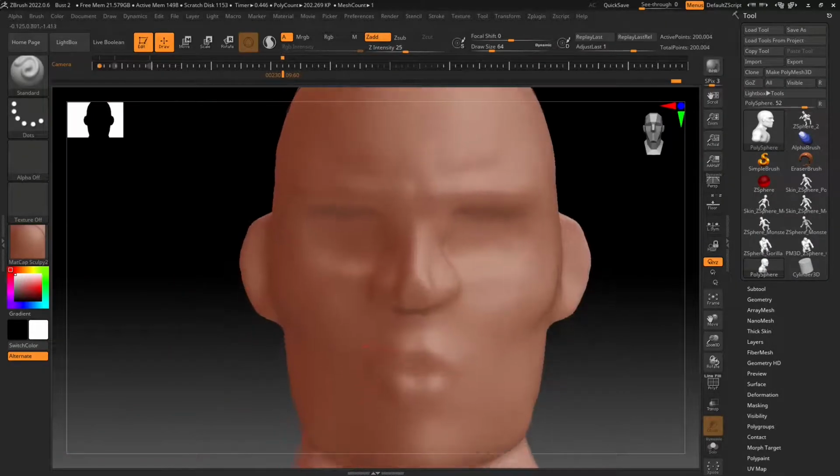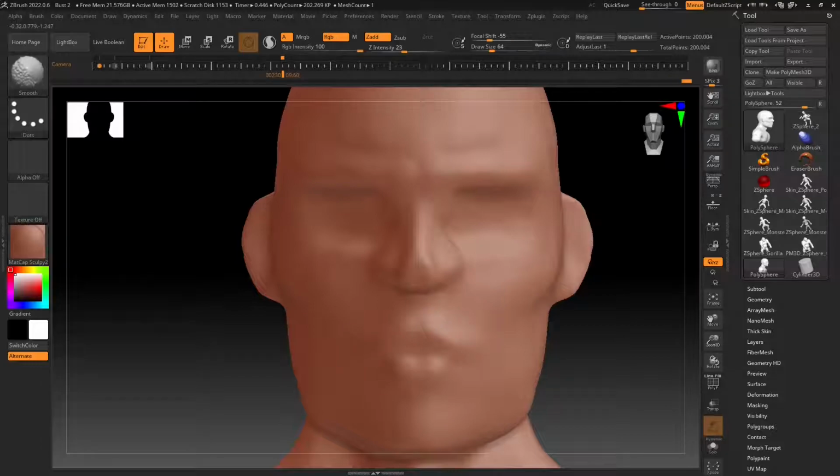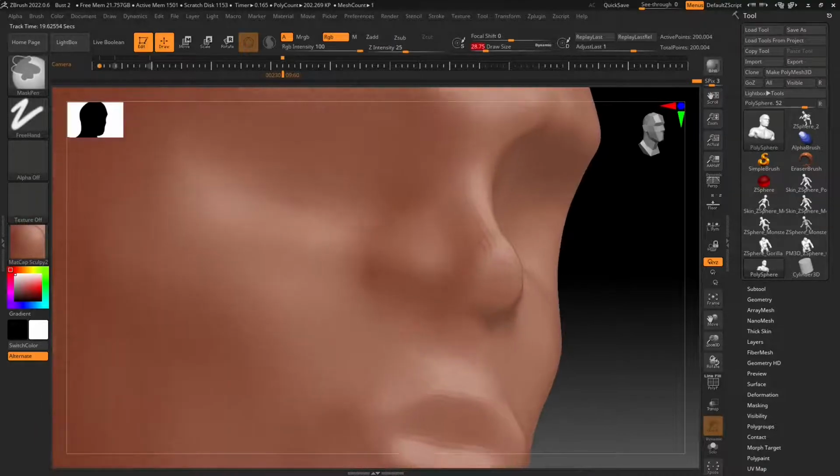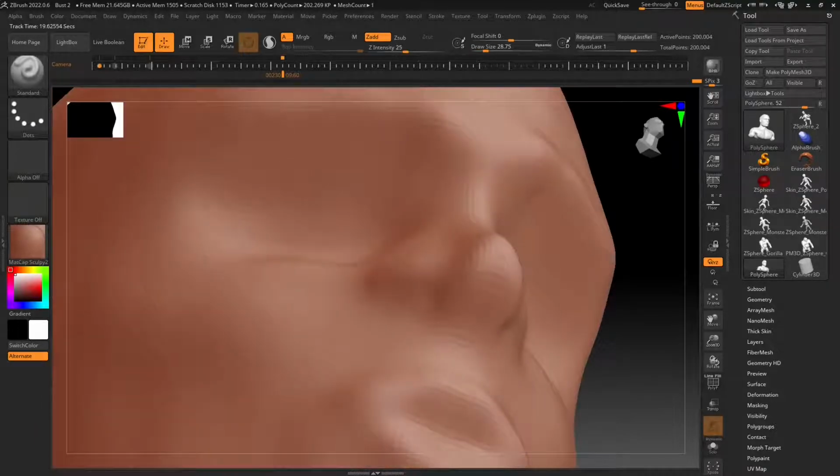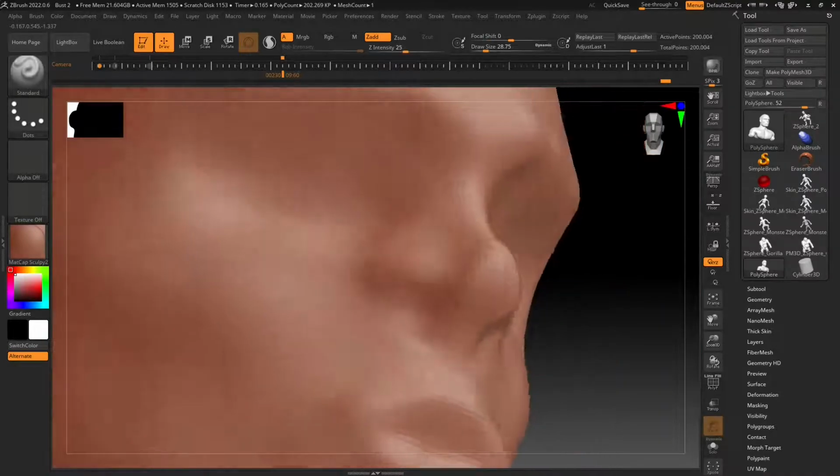So you can see now I'm just trying to sculpt first and then hold the shift key. The shift key, which is the smooth tool, is another really basic and important tool. So probably 50% of the time you're going to be on the shift, which is the smooth. And we also saw that if you hold Alt, you click and drag, you go the opposite, so you're going to carve parts out.